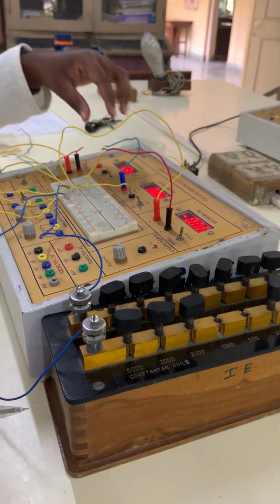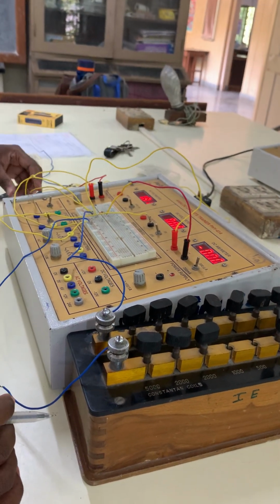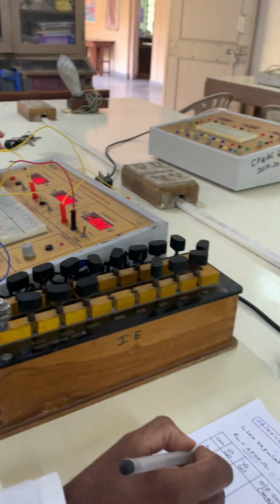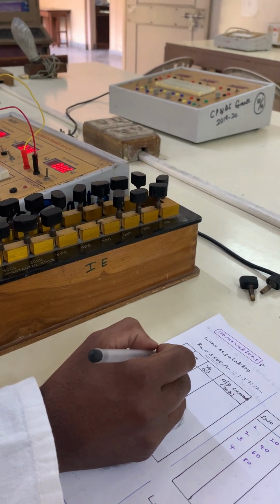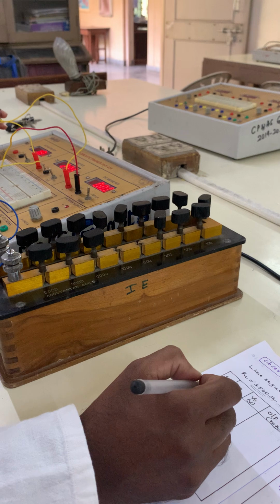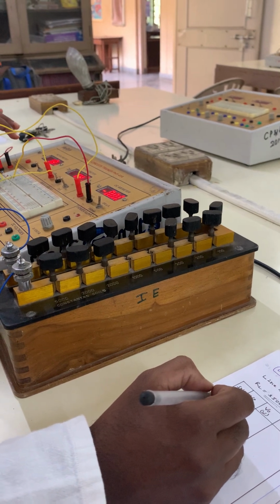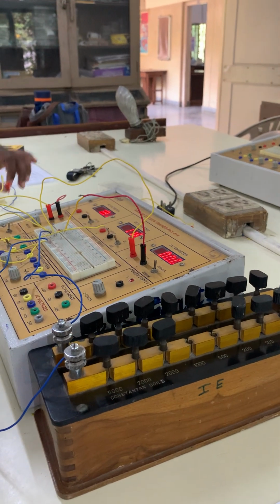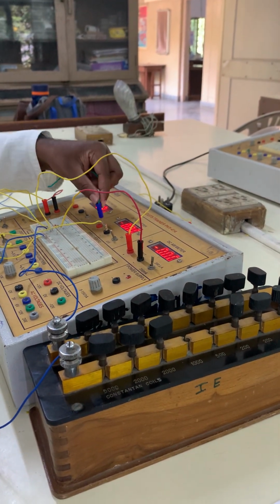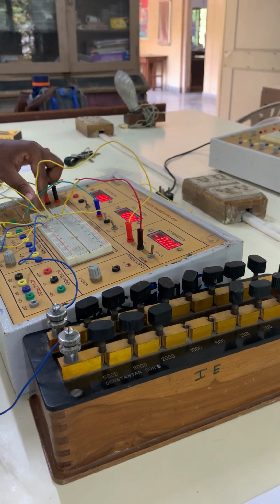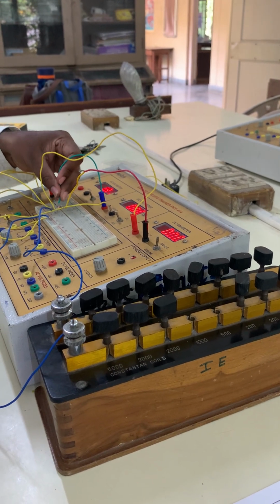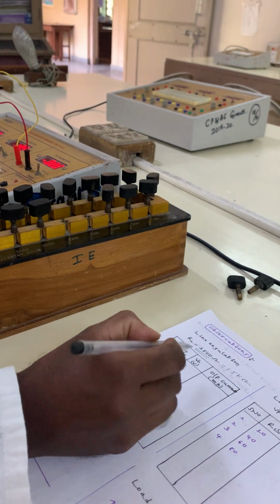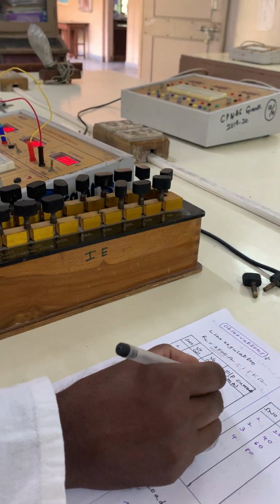So we are keeping the load resistance fixed. Now I am applying the input. How much input am I applying? The input voltage you apply, first 1 volt you have to apply. Clear? Now you see the input voltage is 1 volt. Now you are able to observe the output voltage. What is the output voltage? Here the resistance is there, no? Here you have to keep this, the output voltage also you are getting as 1. So current is equal to 0.